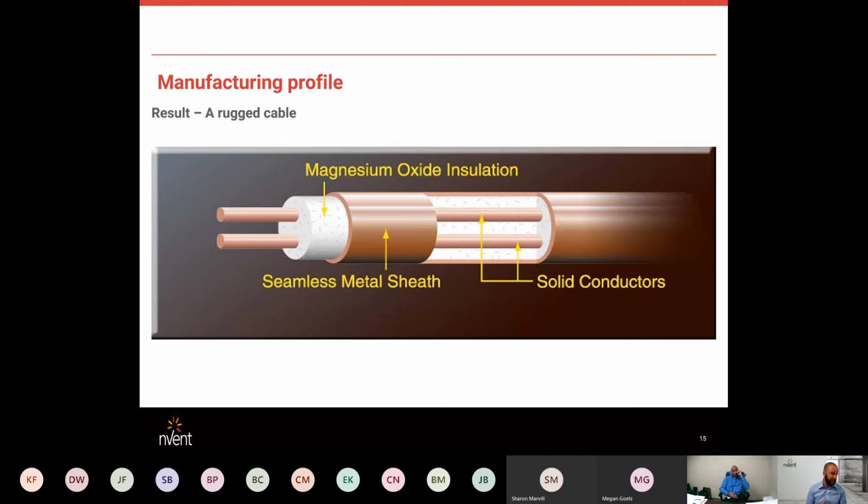They can maintain much higher temperatures and they can withstand much higher temperatures. They can also take a whole lot more physical abuse. So for example, if there's an application where there's high potential of this cable getting hit, knocked around, jammed through the insulation, or stepped on, maybe MI cable is the application because it's just much more robust. You have basically a metal tube jacketing that's very strong as opposed to a plastic jacketing. So you get higher temperature maintains and exposure abilities, as well as a much more rugged product, is what you get with MI cable.